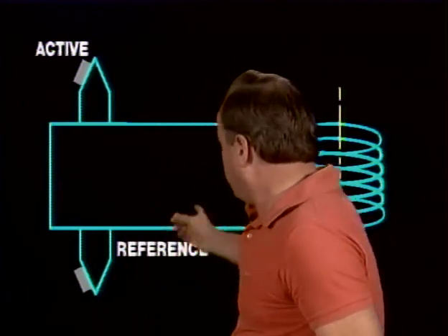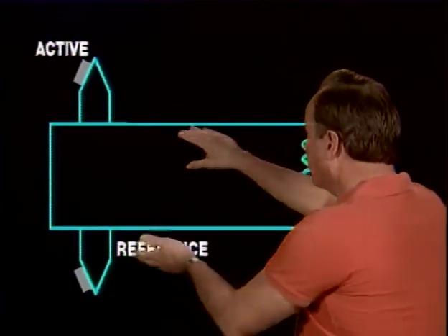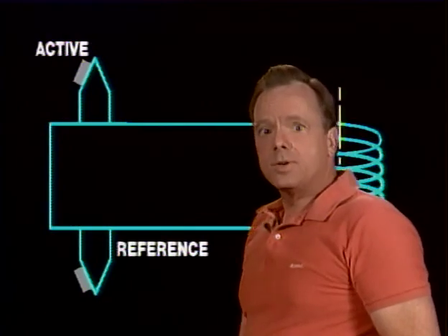And let's assume that you decide to use this thermocouple system for a different use. Can you do that? And the answer is no. Thermocouple leads are designed for a specific installation and may not be altered. You can't change the length of the wire. You can't change the use of it from one airplane to another because you're going to get different readings.